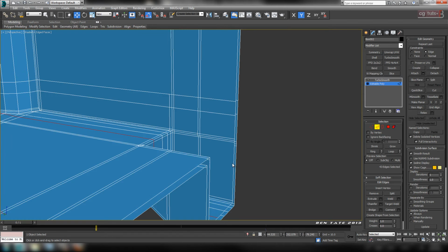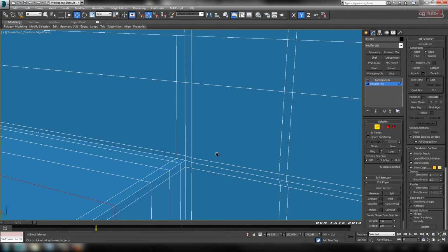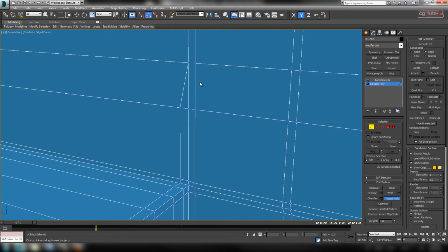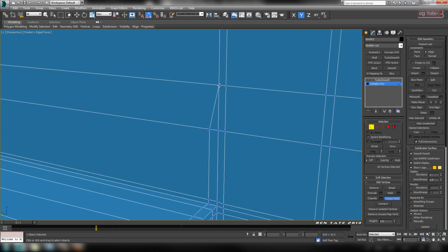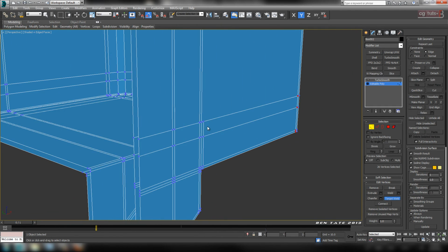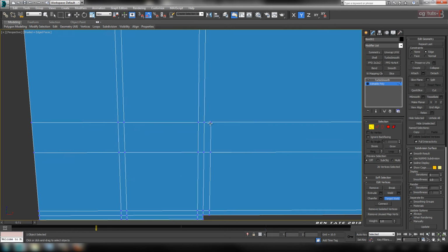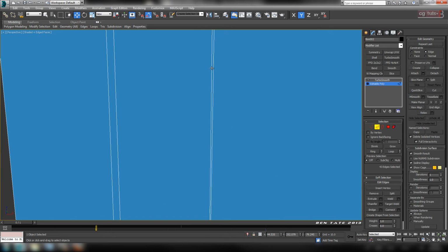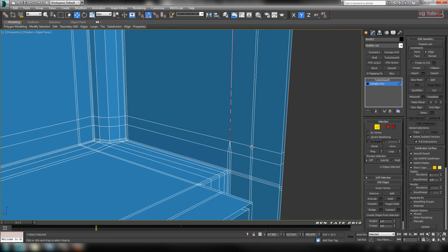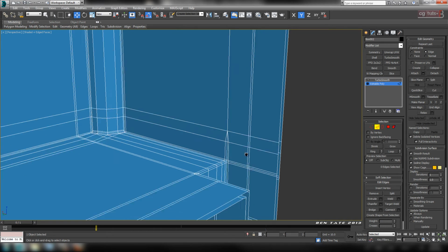And let's go into the inside here and we'll just kind of clean some of this up. Let's go to vertex here. And we're just going to weld this vert here where it ends off to this one. Okay, and this one here to this one. And the same thing on the other side. This one to here, and this one to here. Okay, now it'll allow us to take out this extra loop that we have running up here. The left one here. So just loop that. That should go all the way around to the same point on the other side. So just control backspace that out.